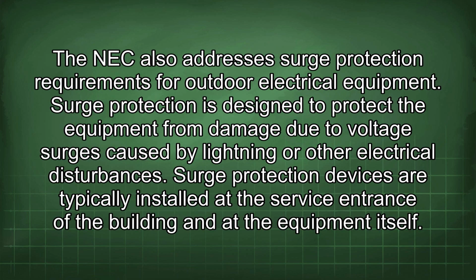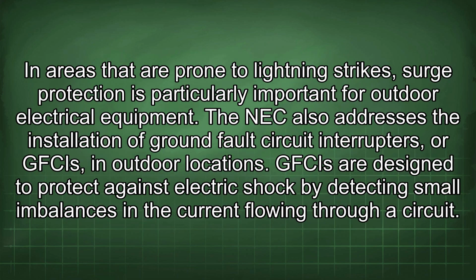The NEC also addresses surge protection requirements for outdoor electrical equipment. Surge protection is designed to protect the equipment from damage due to voltage surges caused by lightning or other electrical disturbances. Surge protection devices are typically installed at the service entrance of the building and at the equipment itself. In areas that are prone to lightning strikes, surge protection is particularly important for outdoor electrical equipment.